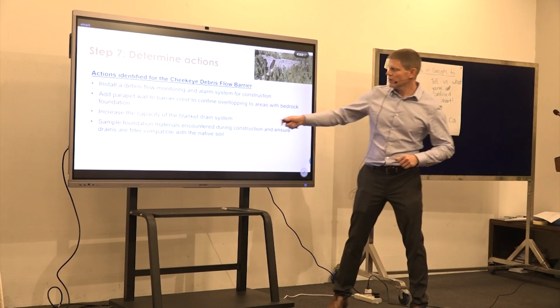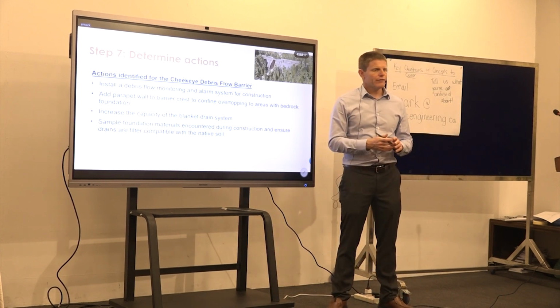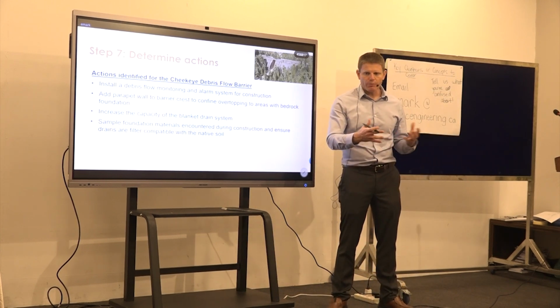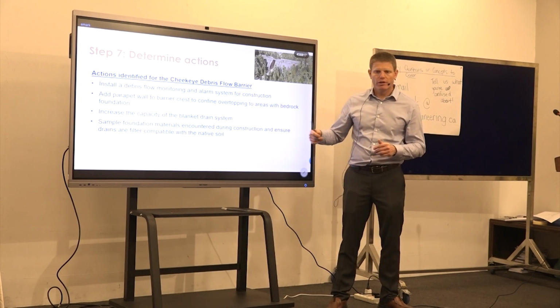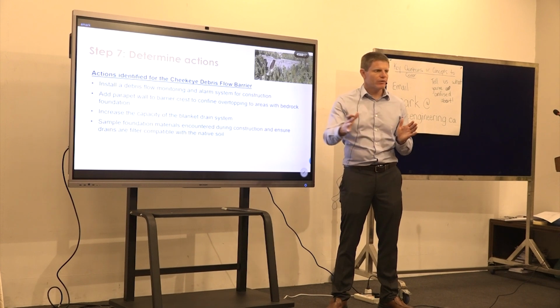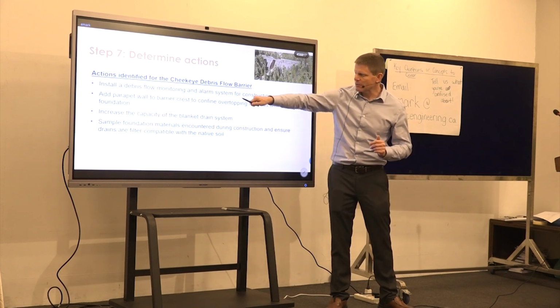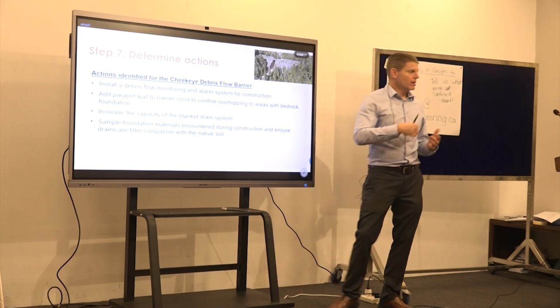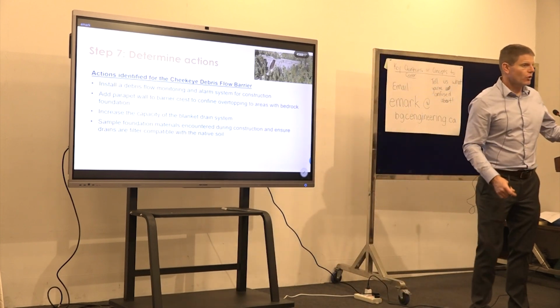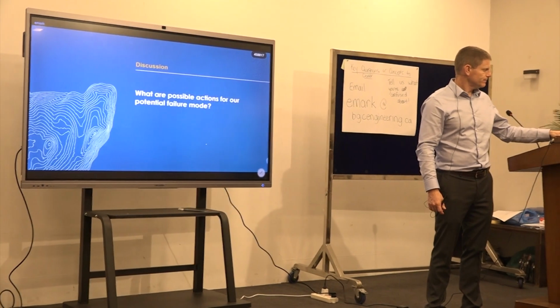And then another point was we didn't know if the foundation materials were compatible or not, and so we did additional investigation during construction to make sure that we have adequate filters. So these were actions that we listed at the end of our potential failure mode analysis for us to carry out to show that we were managing the risks.